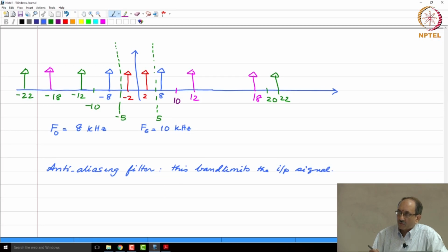because in that case you only lose the high frequency component, whereas if you cause aliasing, not only are you going to lose the high frequency information beyond Fs by 2, but that high frequency information is going to come back as a lower frequency component in the signal and cause distortion. And in practice, it has been found that this aliasing is perceptually very annoying, and hence all practical ADCs have a band limiting filter at the front end. So any ADC chip that you use will always have a front end anti-aliasing filter, and it has been found that this is less objectionable than aliasing occurring, because the high frequency component folds back and appears as a low frequency component.